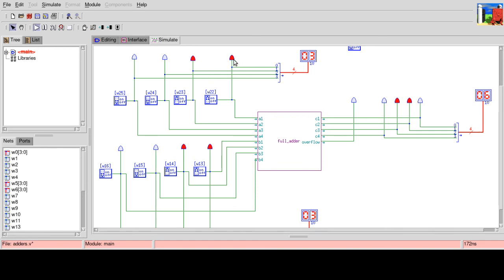Internally, what it's doing is 1 plus 1 is 0, carry 1. Then 1 plus 1 plus 1 is 1, carry 1. Then 1 plus 0 is 1. And then 0 plus 0 is 0, and you get the answer. So it's actually doing all the additions, including the zeros. You would have stopped after there were no more carries and no more digits, but this one will do all of them because all the 3-bit adders are activated. Okay, so let's do another one.